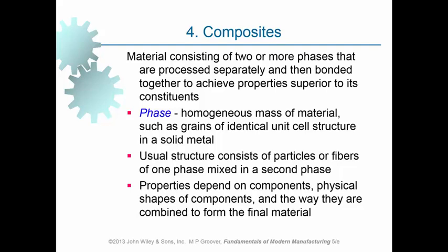For example, we've got a matrix of polymer that is of lightweight, and inside of it there are some particles of a stronger phase that could be particles of ceramic or metallic material that is stronger than polymer, and those are embedded inside of the material in the form of particles that are round in shape, or fibers that have got a long length to diameter ratio.